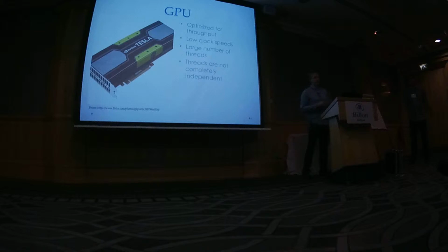GPUs, though, are the tool for exploiting data level parallelism. They're optimized for throughput as opposed to latency like a CPU. GPUs are what are generally used to drive your display in a computer if you have a standalone card as opposed to a software driver. They achieve this by using much lower clock speeds, but thousands of threads. So they're executing a much lower number of instructions per thread, but the number of threads makes up for it. It also leads to power efficiency.